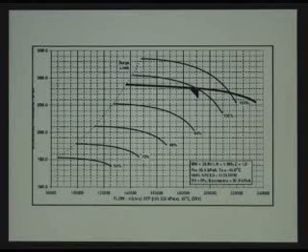But the controllability in this section would be a concern, and we would probably not want to use this kind of compressor curve shape. It would certainly require a change in the trim of the control valve to accommodate the lower pressure rise that it would see in its operational life.